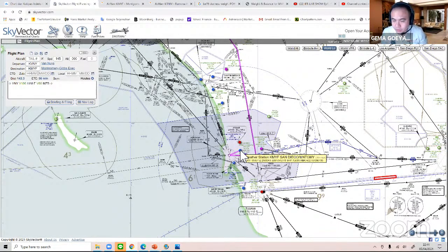Our destination now is getting blue. Why blue? Even though the ceiling now is 1,000 at our destination, our visibility is more than 5 miles. It means when the visibility is VFR and your ceiling is IFR, it's in the middle. So the FAA puts this as marginal VFR. So that's your consideration. But around you, if you can see, Miramar is still IFR, and then Santee is low IFR.